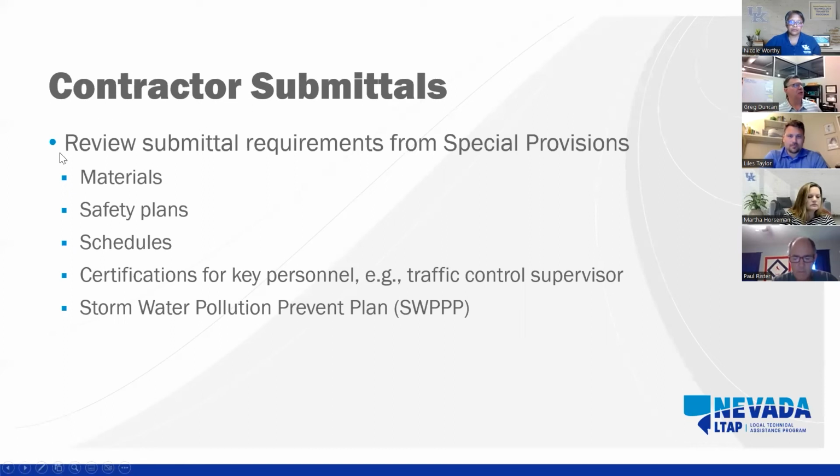It provides for contractor submittals. These are items that are not included in the specific design of the project, but are components that the contractor is required to submit and adhere to. These may be the specific materials that the project is going to be built out of, the safety plans required for their employees and practices, shoring plans for how the work is going to be implemented, and what their schedule is. As was mentioned earlier, there's a completion date that contractors are held to, so they're ensuring that the project can be built within that schedule. What are the benchmarks there? What do we have to have completed in order to get to the next critical item of work?